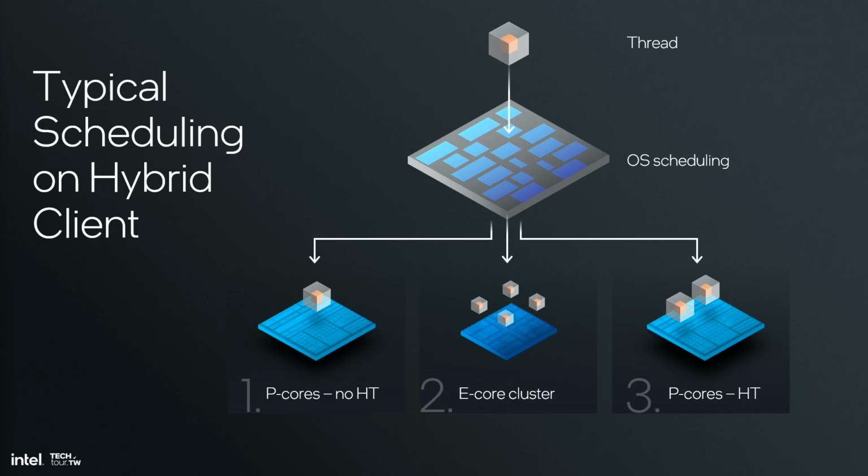In this context, when Lunar Lake architects challenged us to deliver a significantly more performant and efficient P-Core version for Lunar Lake, we took a hard look at hyperthreading. Remember, hyperthreading doesn't come for free. It replicates architectural state. It adds arbitration points along the pipeline.